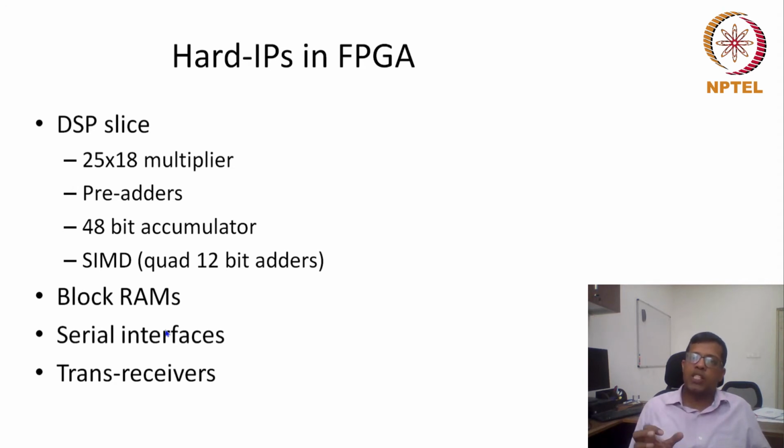For these signal processing applications, people have observed that they require a specific unit which would invariably be required in all different kinds of FPGAs or circuits, which is called multipliers or multiplier and accumulator. Because the multiplier is a very commonly used function in DSP kind of applications, those FPGAs have many multiplier instances as hard or fixed logic.